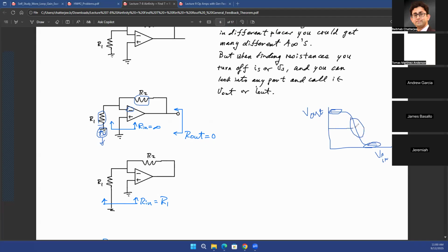That means first you have to start at a DC point, which is almost at the middle of your voltage transfer characteristic. That means almost at the midpoint between your VDD and VSS. So if your VDD is 5 volts and VSS is 0 volts, it's a good idea to have all the DC potentials set at, let's say, 2.5 volts. Right? Then only you can expect gain, because then you are in the middle of this voltage transfer characteristic. And then if you have a small perturbation in the input voltage, if your gain is more than 1, you'll have a large perturbation in the output voltage.